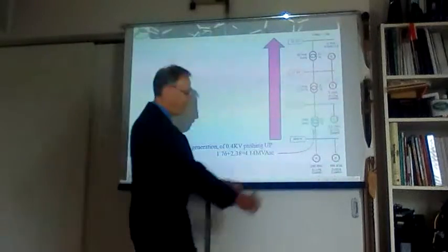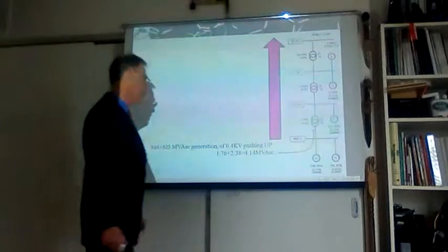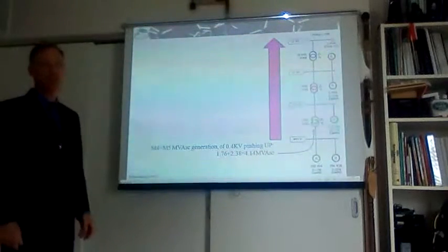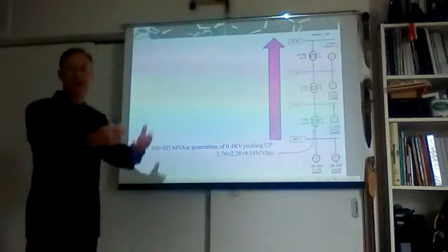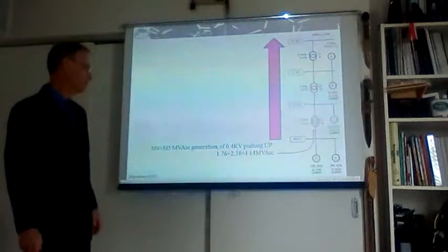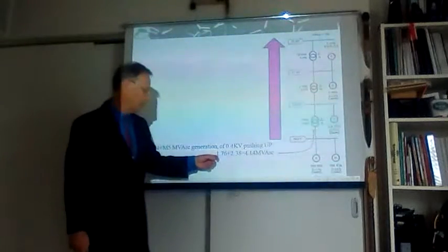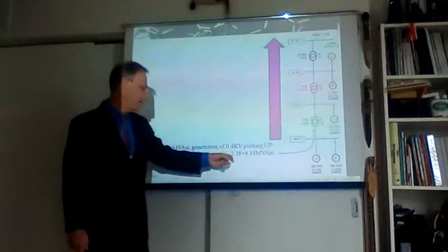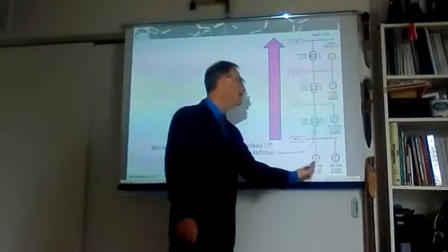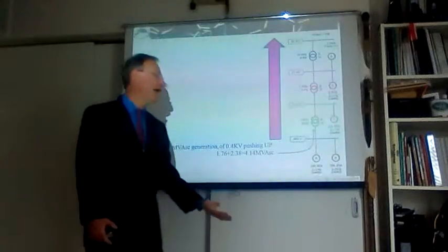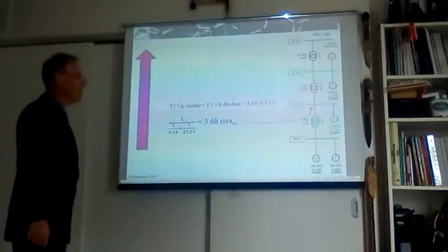We reverse direction. When we go up, we see the effect of those two motors back on that transformer, and we repeat the same calculation, collecting all the currents and MVAs going up. The total of the two motors, as calculated before, 1.7 and 2.4, altogether 4.14 MVA hitting back as a backsplash into that transformer.